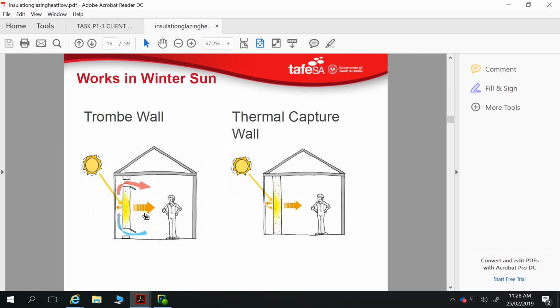On the western side, it's going to get blasted by that heat as the sun is setting, and then heat up your house in summertime at night, which is also what you don't want. So east and west, I'd say certainly no. Northeast and southwest, yes, possibly in a cooler climate where you can control the shading. You can use it to your benefit.